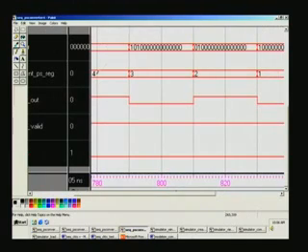You can see again it was at 4, so it is a left shift. So one must get dropped, and one must also go through the output, and this is taking place here because shift happens here, but it will get reflected only at the positive edge of the next clock. And so on it goes.